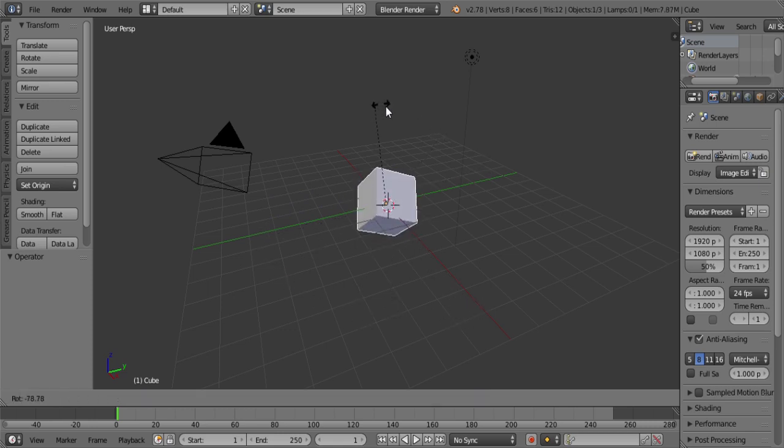If you rotate and you press X, its axis of rotation is the X-axis. I can also press Control and now I'm rotating in steps of 5 degrees around X. If I press Y, it's rotating around Y, Z. There you go. So during the operation you can press X, Y and Z, whether you're grabbing, scaling or rotating, doesn't matter. You can do that with any of these transformations. I'll just right click again and it's back.